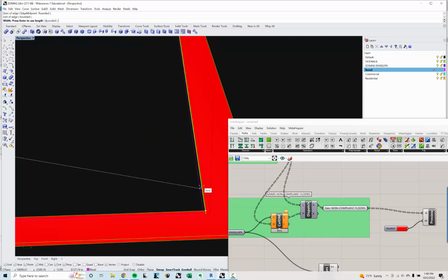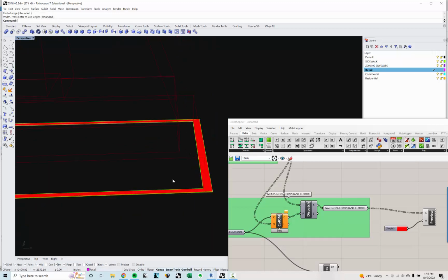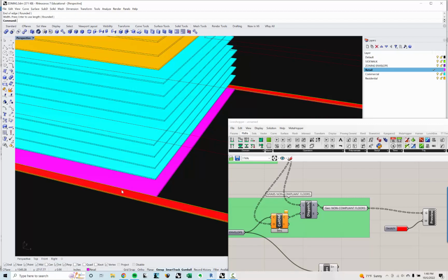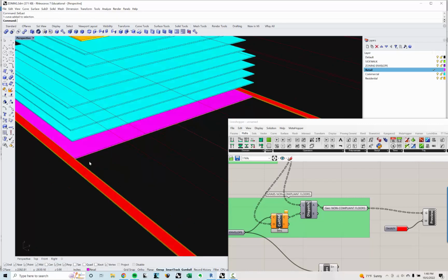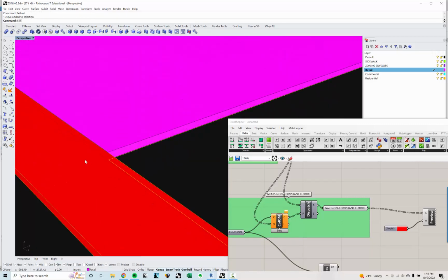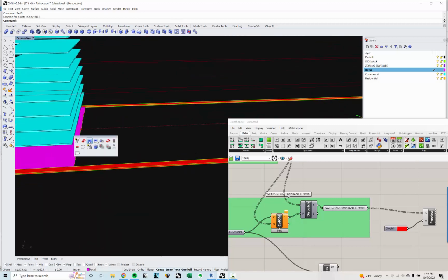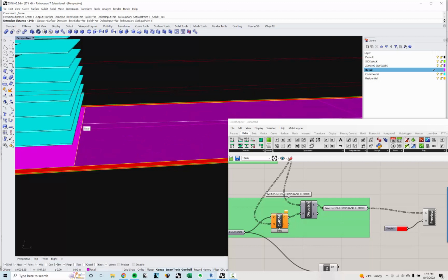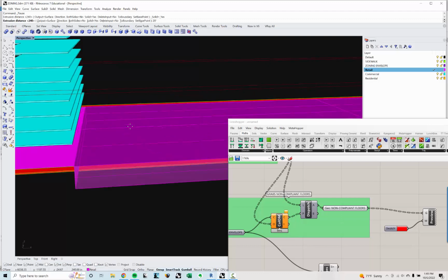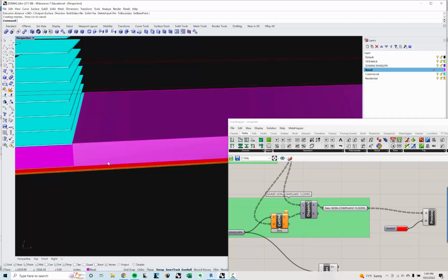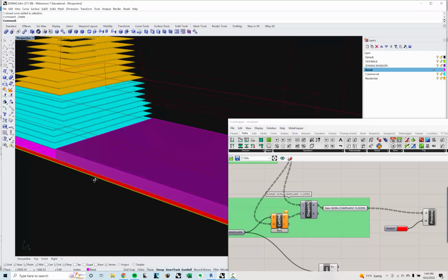You know, just for this, select that curve. I'm going to use what I like, the set point component. Set everything in the Z to align to the world. That'll make sure it's all right at the top of the sidewalk where I want it. And then I can just extrude this up, and let's say this is like 20 feet, so it aligns with the top of my other program.